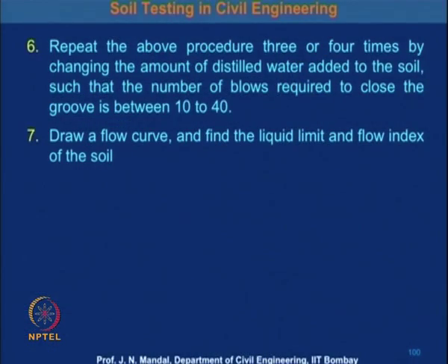Next, you have to repeat the above procedure 3 or 4 times by changing the amount of distilled water added to the soil, such that the number of blows required to close the groove is between 10 and 40.